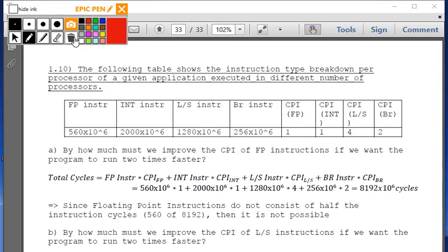So the opcode goes to a control unit, which is a controller, which is a bunch of state machines. Some of them go to registers, which are local copies of cache. Some of them go to sign extension, and then they're all sent to an arithmetic logic unit, which has no memory elements, it just performs executions. And then you can either go to data memory or be written back to the registers.